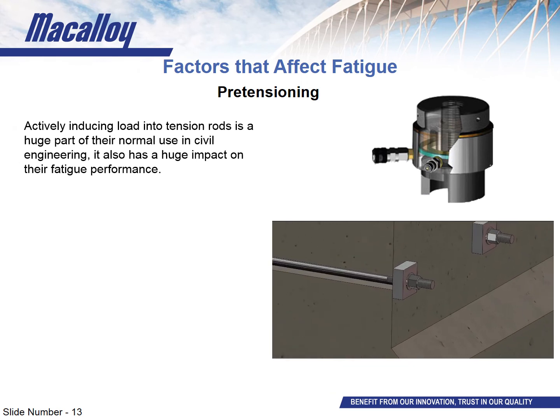First of all, you've got the ring spanner, which allows you to rotate the nut. Then you've got the bridge coming in, which actually gives access to the ring spanner, the jack that provides the force, and the puller that connects it all together. That puller is then pushed outwards by the jack, and then the nut is rotated via the ring spanner to lock that load off.